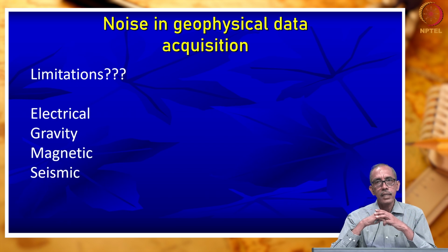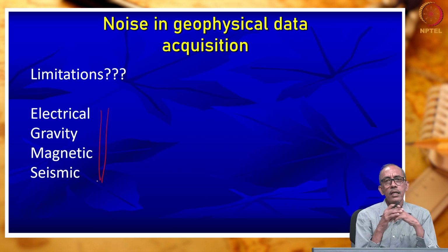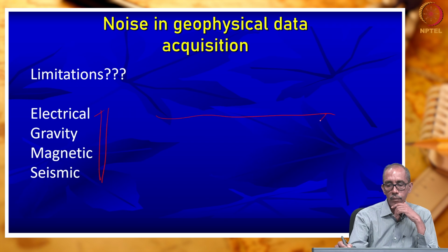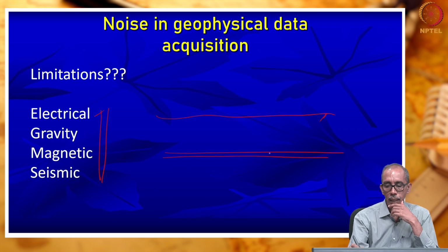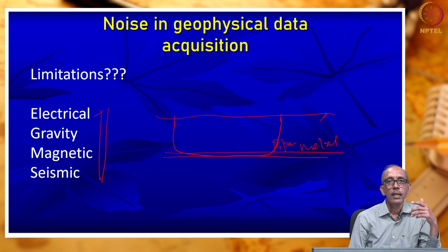Lastly, what are the limitations? Always we should also understand the limitations, right? Broadly, we have touched upon some introduction I gave you on these three methods. What are all the limitations? If you take electrical methods, when you conduct the survey on the surface, suppose there is a buried metal pipeline made of metal, the current which we apply will essentially pass through this metal, isn't it? So, it will give some spurious results to us, right?